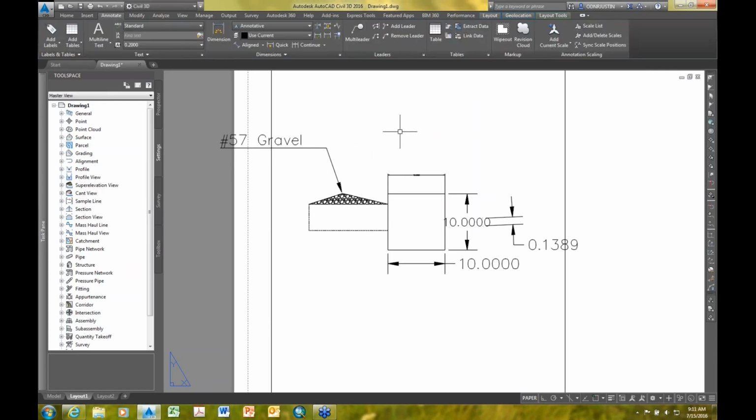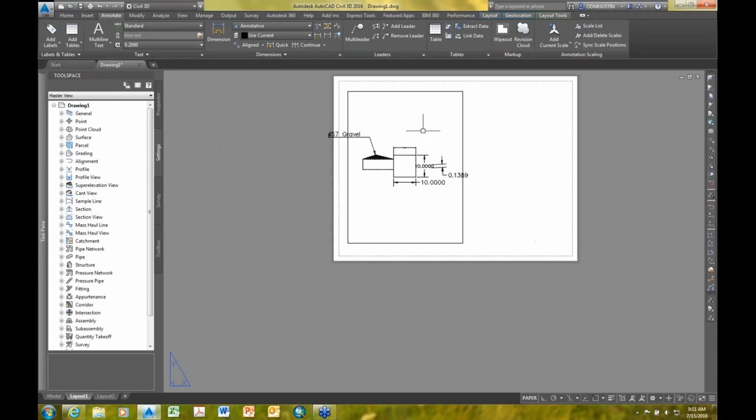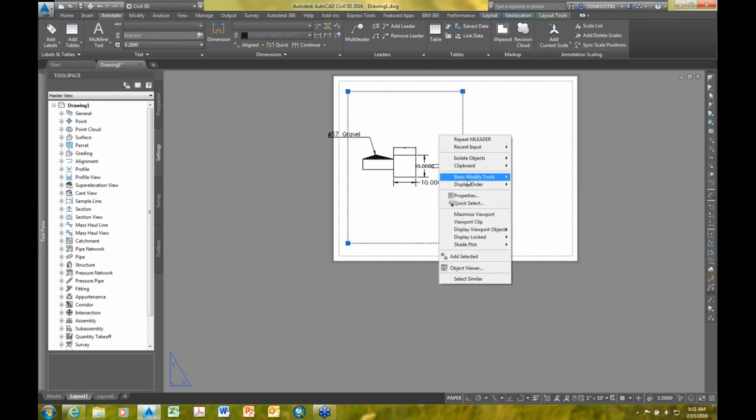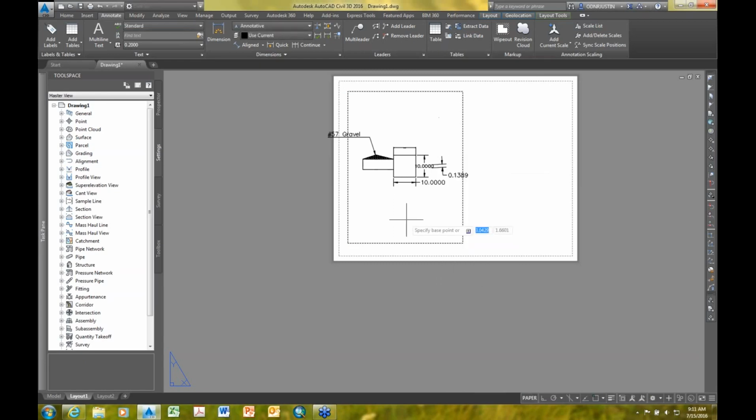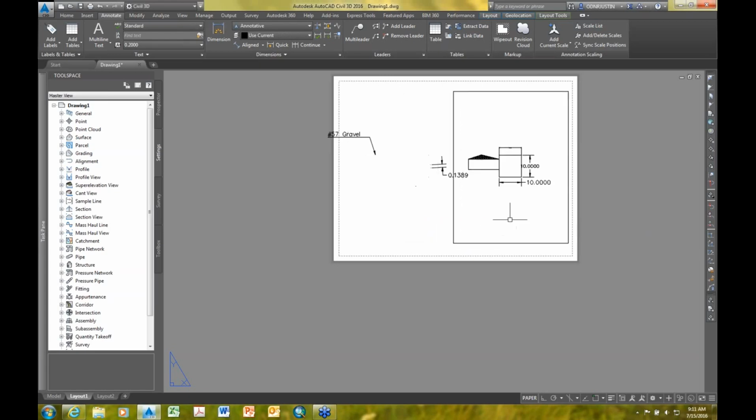And it'll draw in to label any features that we want to specifically call out. The problem with doing that is if I decide I need to do more drawing work, I'm going to take this whole viewport and shift it over to this page. My drawing items are separate from that viewport, both the dimension and the leader that I drew. So I have to make sure I move those along with it.